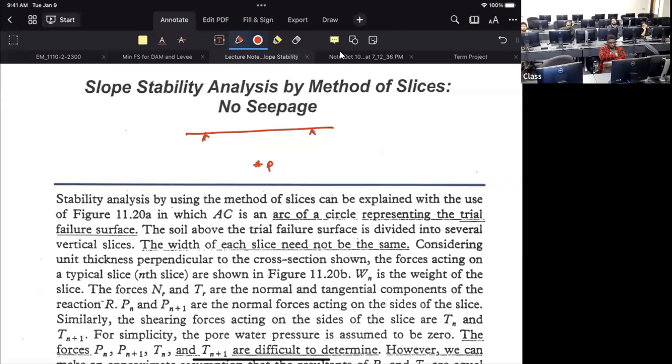Earth pressure comes from the gravity, right? The weight of the soil, right? So at this point P, you have a height difference H, okay? So all the soil on top is putting pressure on this point, right? So what is your pressure? Sigma V, gamma H. That's your sigma V. What is your sigma H?